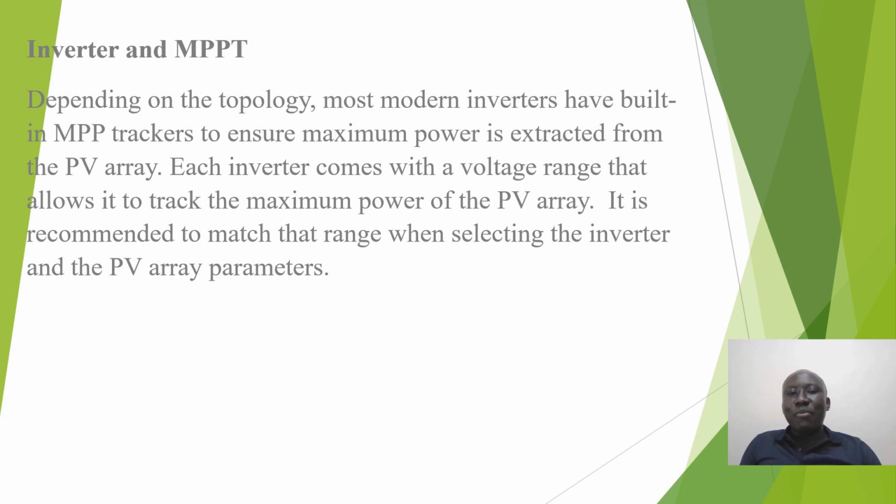Each inverter comes with a voltage range that allows it to track the maximum power of the PV array. It is recommended to match that range when selecting the inverter and the PV array parameters.